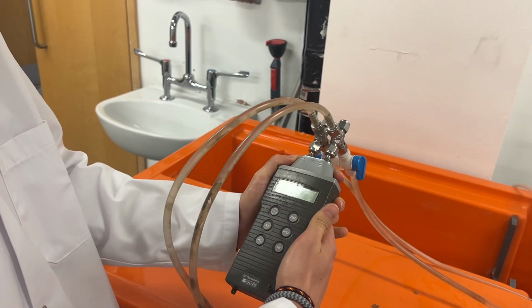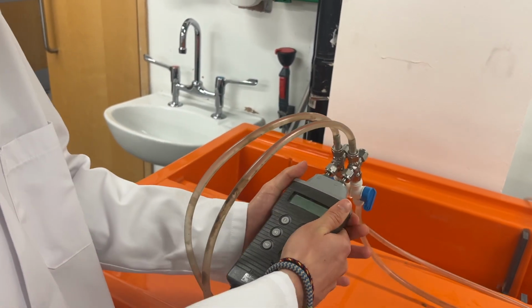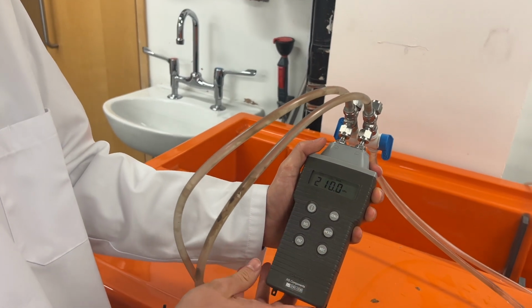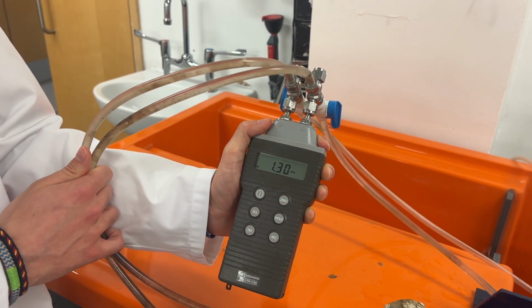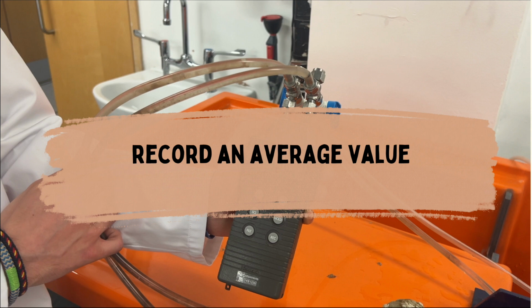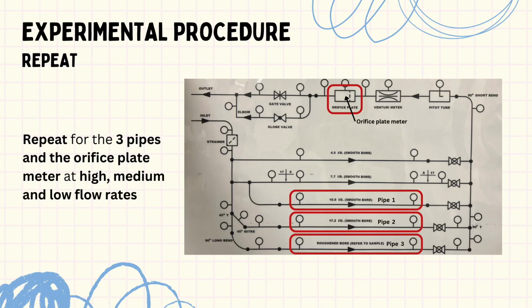Finally, the valves of the manometer must be opened and the device switched on by pressing the power button. The manometer will display values that fluctuate rapidly, so an average value of the pressure drop should be chosen and noted down. Repeat the previous steps for the 3 pipes and the orifice plate meter at high, medium, and low flow rates.